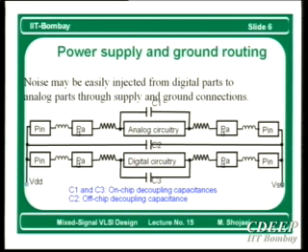Now here I'm talking about VDD and VSS. So we have this inductor connected from this VDD pin to the internal pad, which is the internal VDD pad. Then there is a small resistance here. Then it goes to the analog circuit. The same VDD I'm using, I'm giving to the digital circuit. First of all, I can have two different pins, but at the end I connect them together. Then that means that I have externally on the board a single VDD, which supplies my chip.